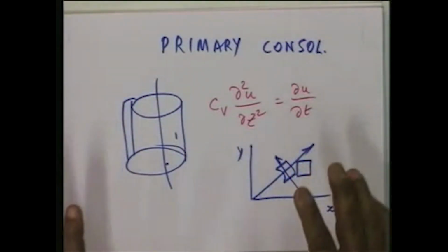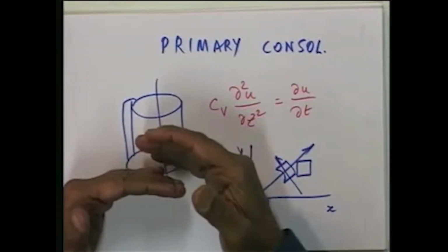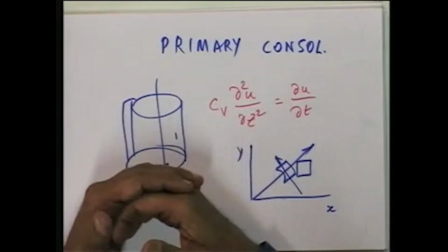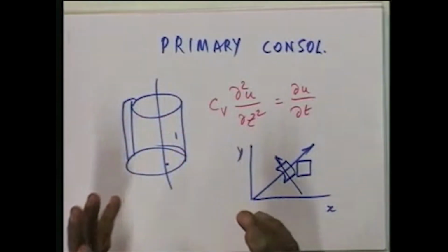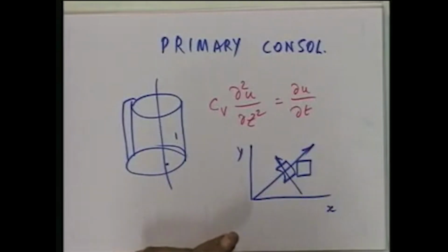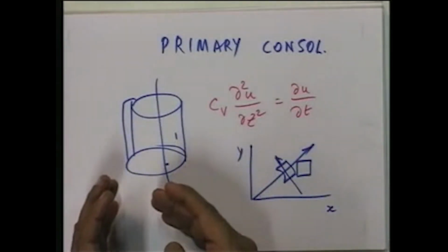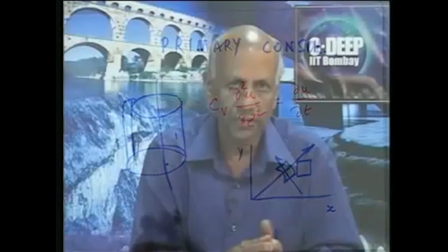What this means is, our 3-dimensional problem in terms of polar coordinates can be treated as a vertical compression problem corresponding to the same z coordinate as in the Cartesian system, plus a consolidation which is now a function of the radial coordinate r.